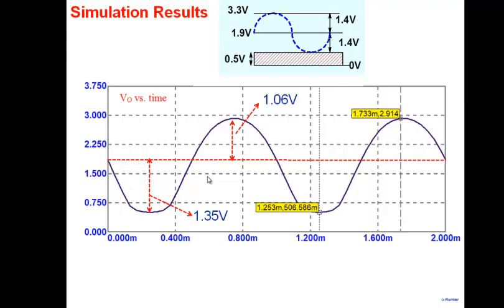So what I'm trying to tell you is, most of the textbooks that you will read say, okay, maximum swing is 1.4. This is the level of discussion that you'll have. Maximum swing is 1.4. And then you go and build an amplifier in the lab or you simulate it, you'll not go to 1.4 at all. You'll never reach 1.4. It will be very hard to reach 1.4. Even at 1.06, you are seeing it's so distorted.